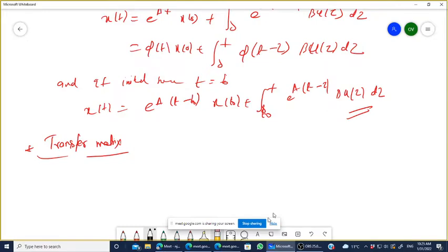So just see, you have a command in MATLAB also, ss2tf, I think. You have to define the A matrix, B matrix, C matrix, D matrix, and then you will write this. Then your code will run.